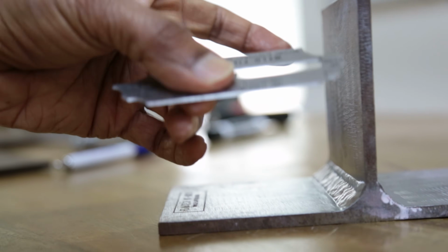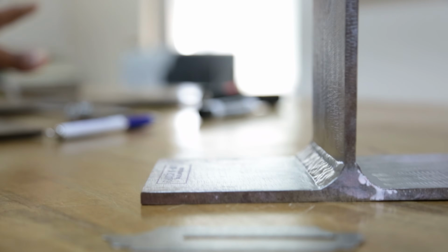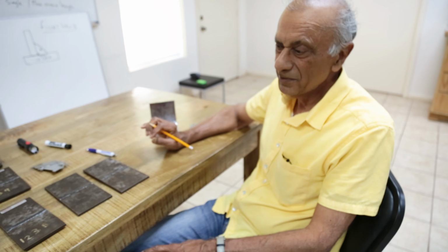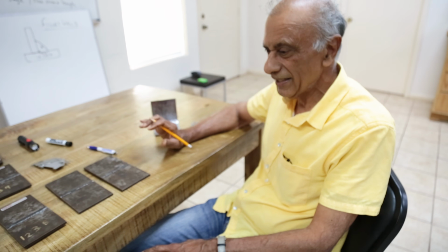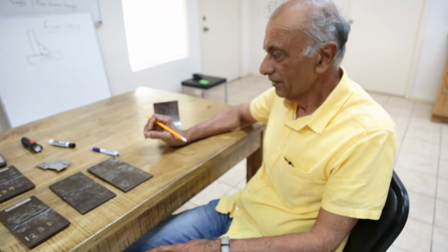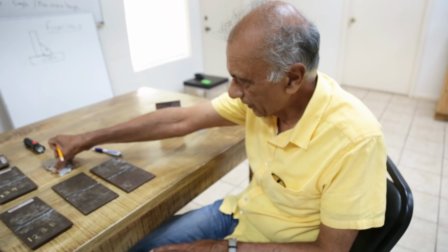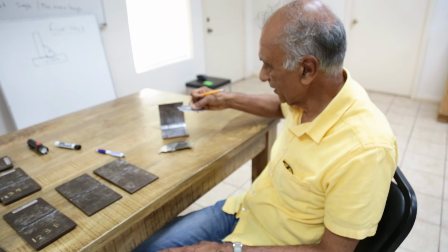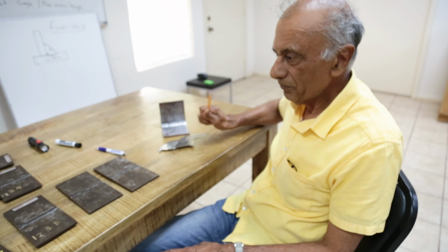For the fillet weld, all you need is the fillet gauges. You don't need all that measurement stuff for these gauges. Finally, what I wanted to say is that with experience and with the skill, most of the weld you can just look at it and say they are acceptable or outright rejectable. You have to have these gauges with you for the inspection, and use them when something you're not sure is acceptable or rejectable, and it's borderline. All you need is simple gauges, just like this one, and this one comes in various sizes. And make sure you have a good data sheet to document all your reports.